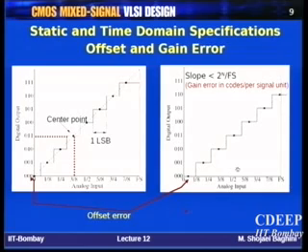That will give you the offset error. Fortunately, offset error can be compensated easily because you can compensate the offset of the comparator, for example. So it is possible to trim and adjust the offset and bring the characteristics back to the original case. So that is not a big issue eventually.